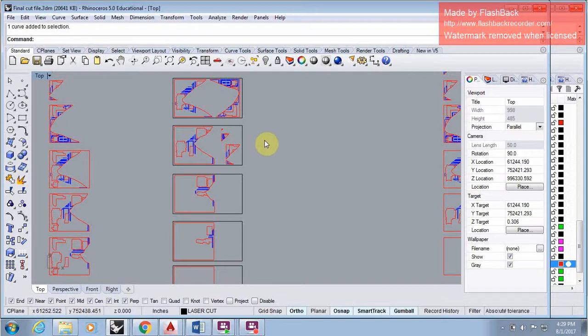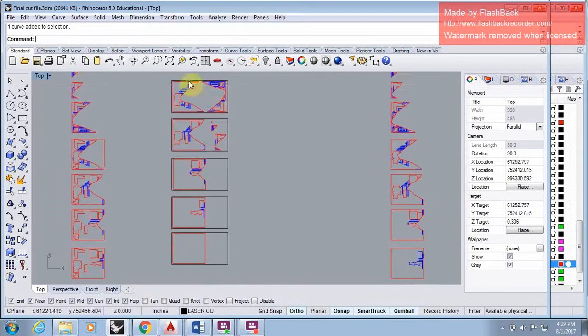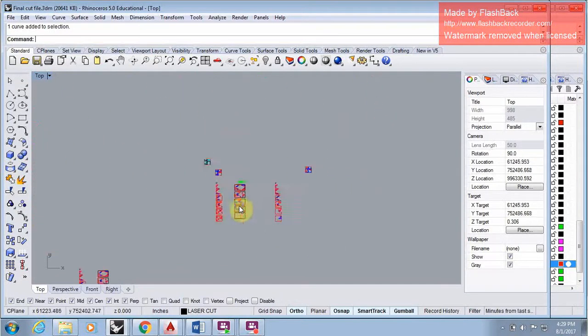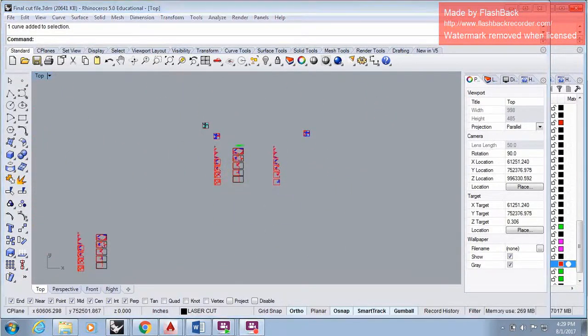Note, the laser cutter dimensions are 18 by 32, so be sure whatever material being used falls between this dimension. Organize all cut pieces so that they can fit into each respective material boundary in order to save on resources, as you see here. Follow the topography grid in order to distinguish the amount of sheets required.